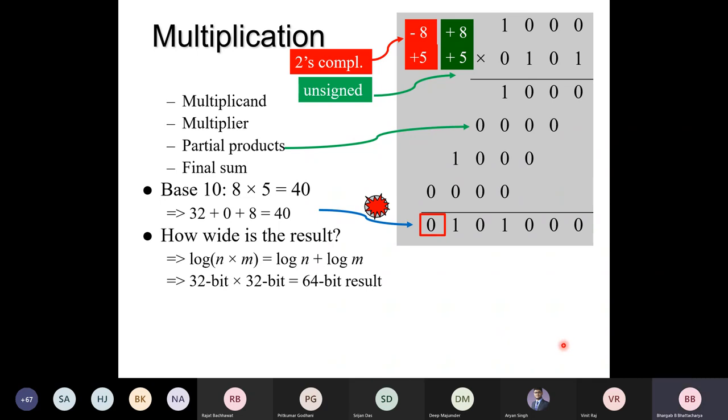So we have observed many things from this simple table: multiplication involves computation of the partial sums, which is nothing but computing the AND operation bit by bit. Then we need to add all these partial sums, which boils down to the same problem as carry save addition. The size of the final result would be twice as long as the input size.